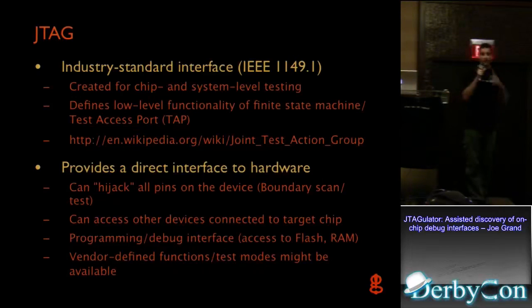First, because it was designed for what was called the boundary scan test, to test each individual pin, you can control every single pin, either drive signals out on every single pin or read data in on pins that are inputs or outputs. So that's pretty cool. And because you can do that, you can now hijack other components that are connected to that device on the bus. So say if you're accessing a CPU through JTAG, and that CPU is connected to a piece of flash memory, if you can twiddle those bits of the CPU, now you can communicate with the flash memory and try to suck data back out.